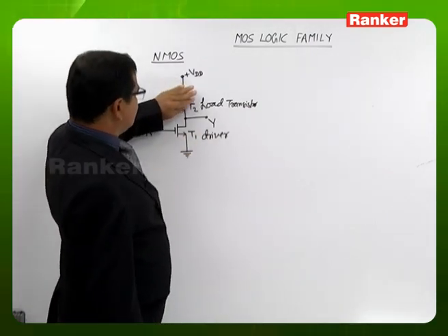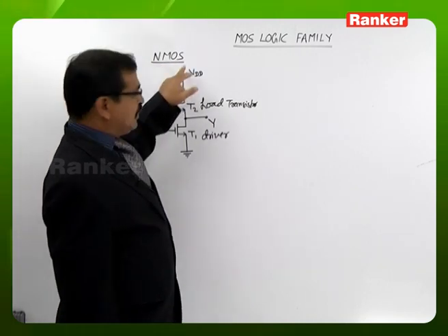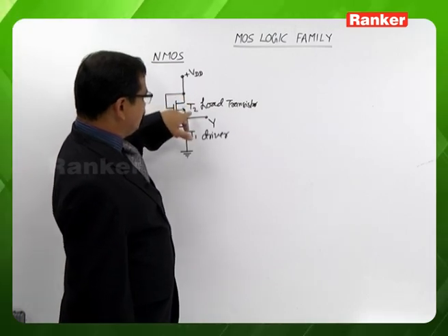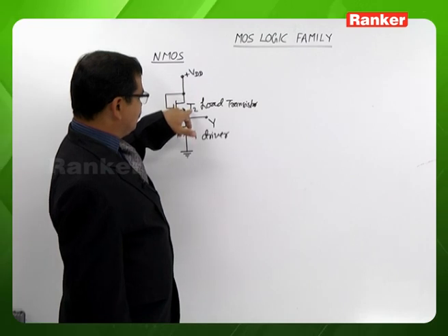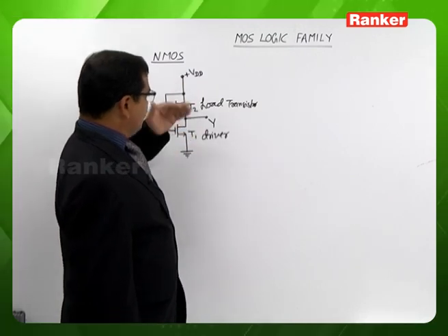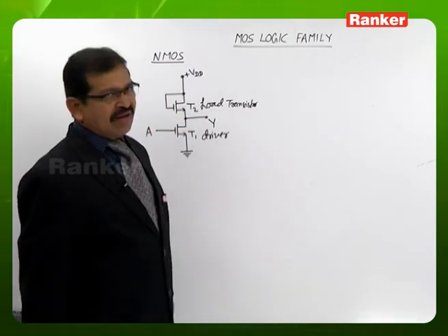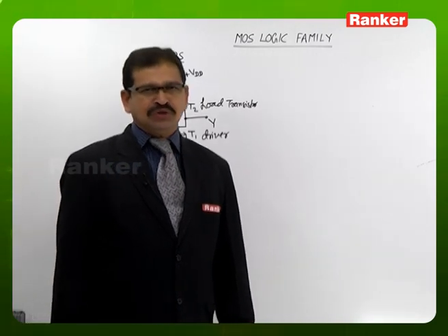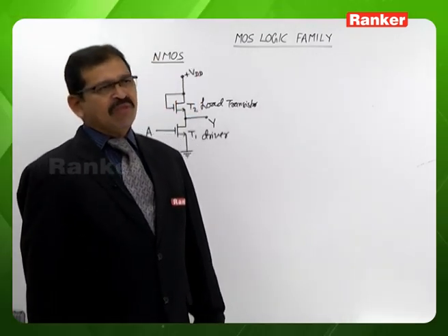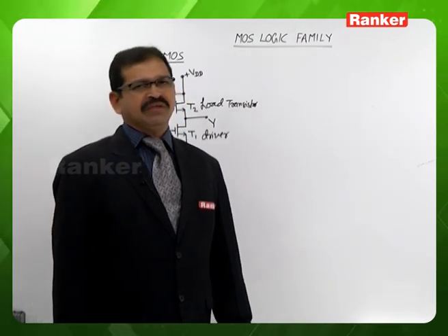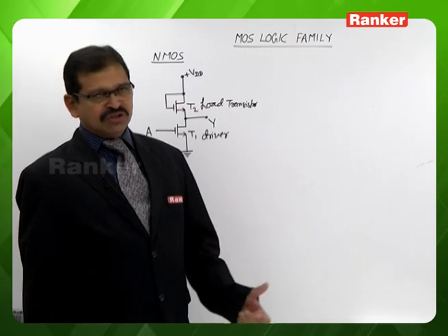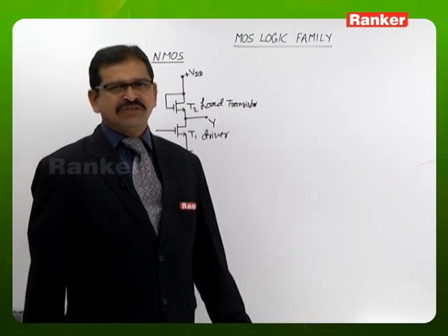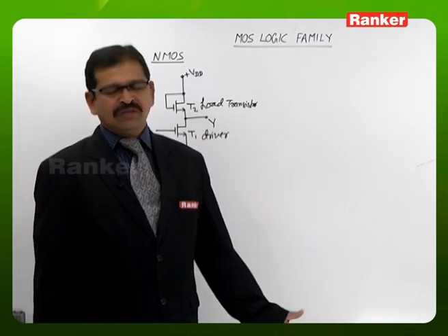Conventionally, instead of this transistor T2 we could use a resistor. But instead of a resistor, we use this N-channel MOSFET itself in the place of the load resistor. While using the MOSFET, the advantage we have in the IC form is that the MOSFET takes less silicon chip area compared with the passive resistor. Hence, in integrated circuits, wherever we are in need of resistors, we use MOSFETs in the MOS Logic ICs.